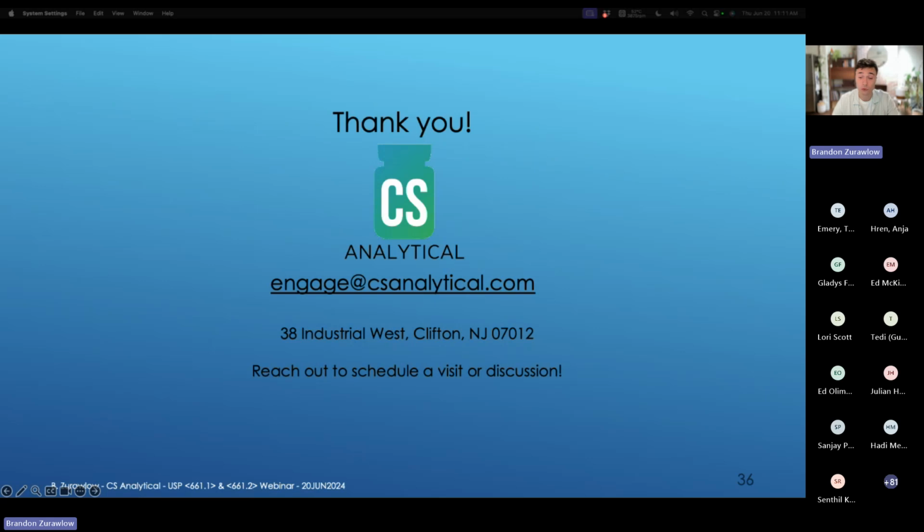There's the concept of brimful capacity, overflow capacity. And so, frankly, across the different USP chapters, there are a lot of different potentially conflicting ways in which volume is expressed. Realistically, the way that I've seen 661.2 performed on these types of package systems is based on the nominal volume of the package system itself.